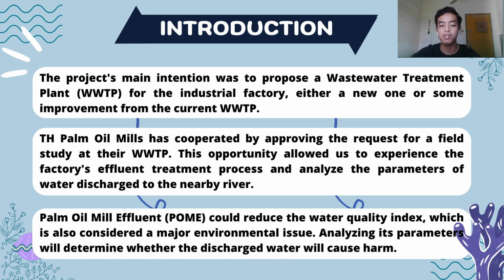Tabung Haji Palm Oil Mills has cooperated by approving the request for a field study at the WWTP. This opportunity allows us to experience the factory effluent treatment process and analyze the parameters of water discharged to the nearby river. Palm oil mill effluent (POME) could reduce the water quality index, which is considered a major environmental issue. Analyzing its parameters will determine whether the discharged water will cause harm to the nearby river.